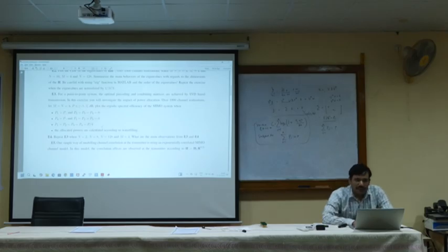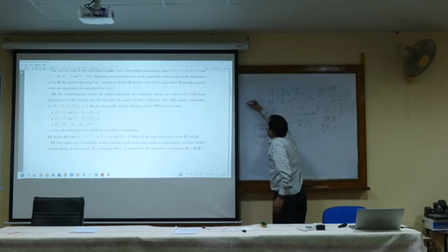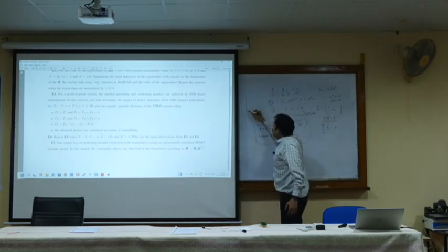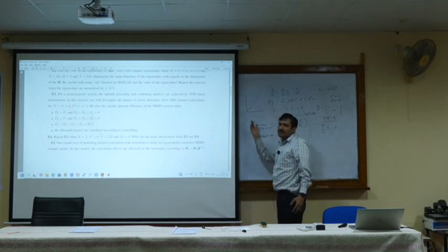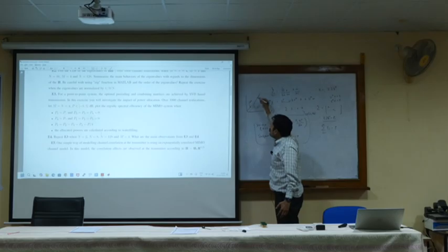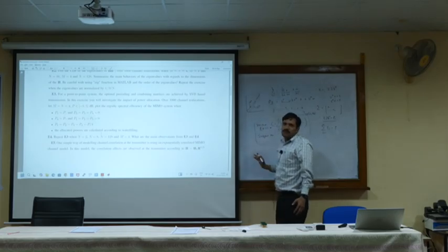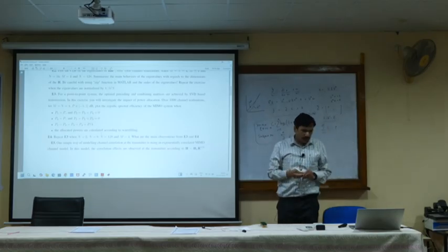So here in the water filling, let me tell you what we will see. We will see the result like this. Water filling will have the highest rate as we increase the SNR, and equal power allocation is like this. So at high SNR, equal power allocation and water filling both will merge into one. So at high SNR, equal power allocation is optimal. That's the conclusion here.